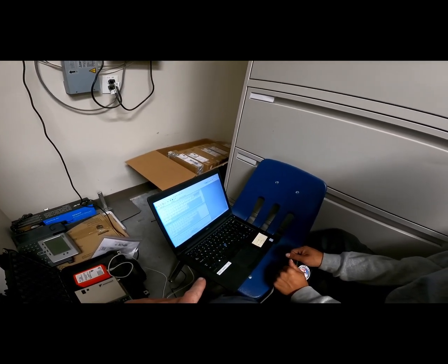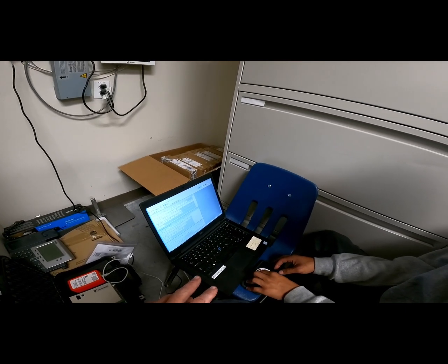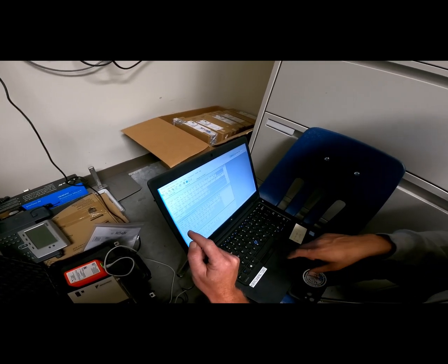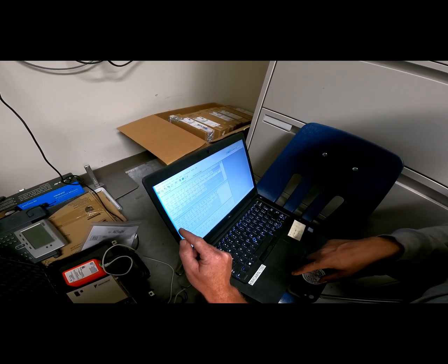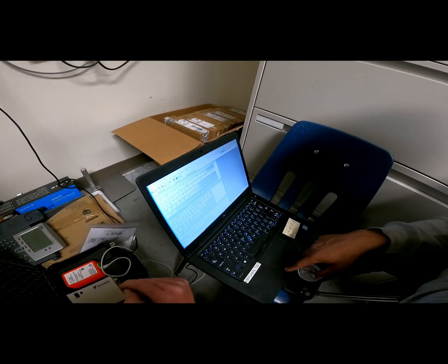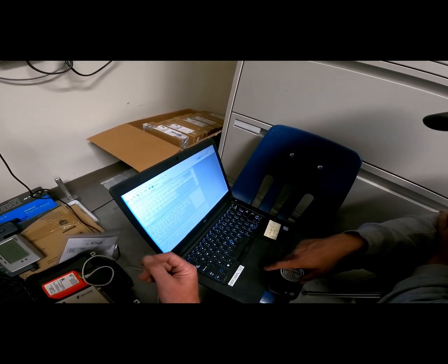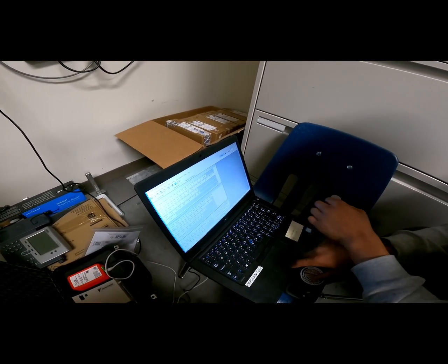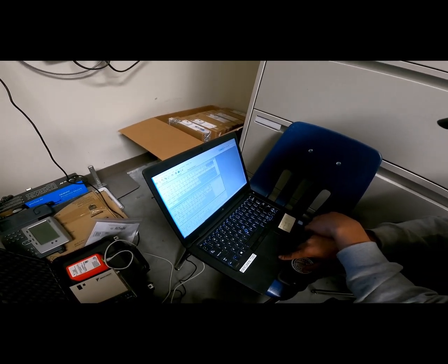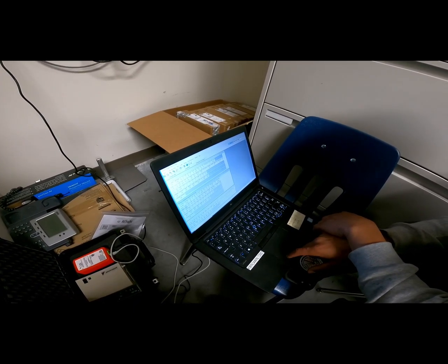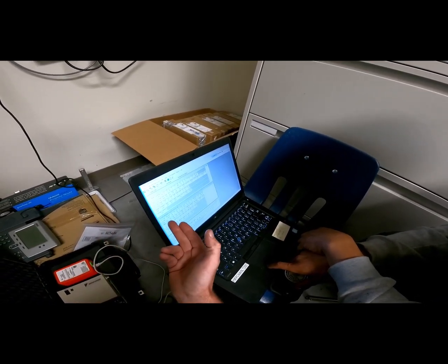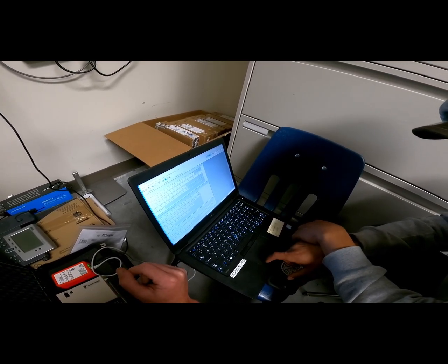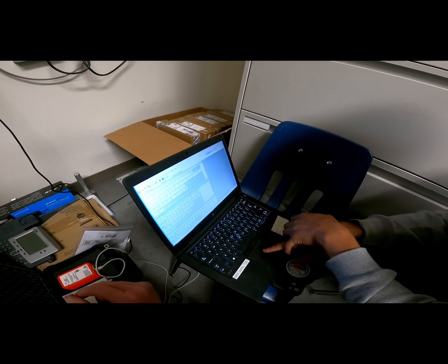One thing I like to do is highlight the values that I want to see. So since this unit is running, you're going to click on the actual value, not the name of the sensor. So 63HS1, that's your high pressure. That'll highlight it. That'll allow you to look at it faster when you've got a lot of stuff here to look at. Highlight 63LS, that's your low pressure. Now you want your saturation temperatures that correlate to those pressures. TC is the temperature of the condenser. That's your saturation temperature on the high side. TE is your saturation temperature of the evaporator.